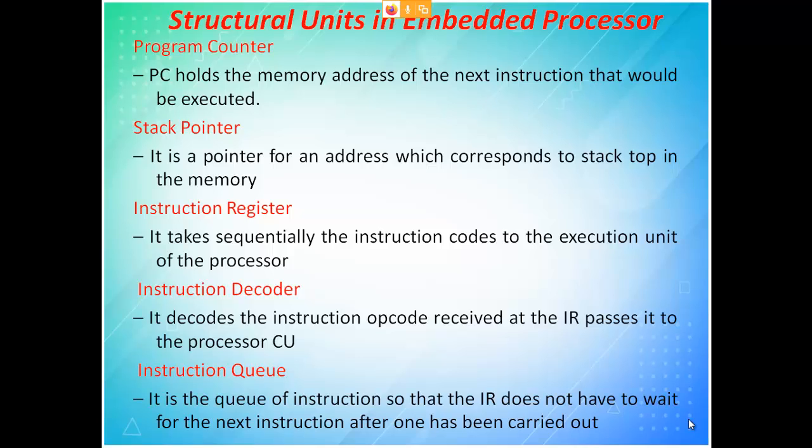Now what you are going to do? You are going to jump to a location, say 8000. So after jumping, after completing the work, where do you have to come? Again you have to come to 6001. But the program counter will be loaded with 8000 now. So the value 6001 will be moved to stack, and then the new value will be loaded in the program counter.